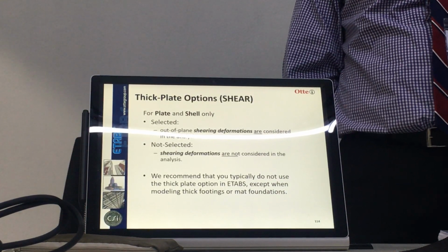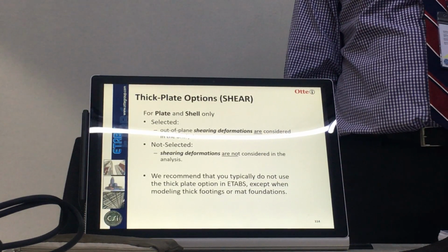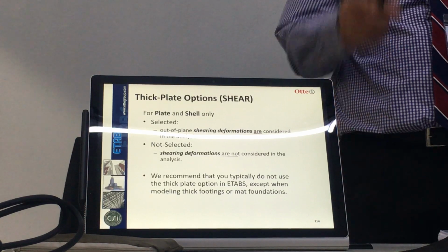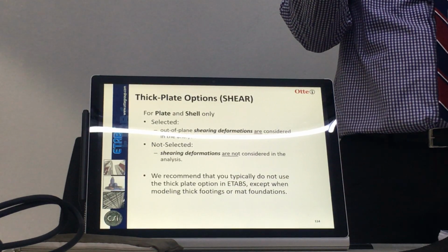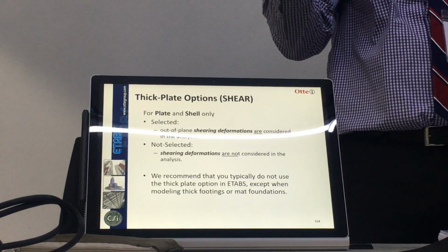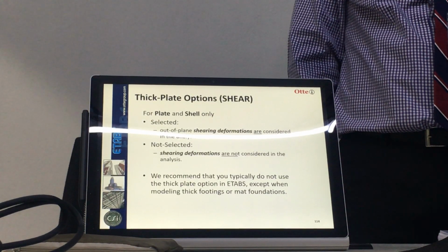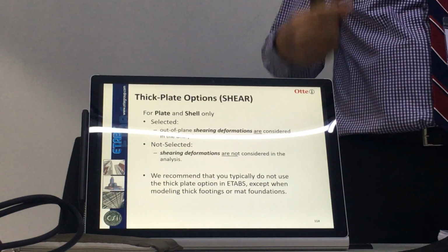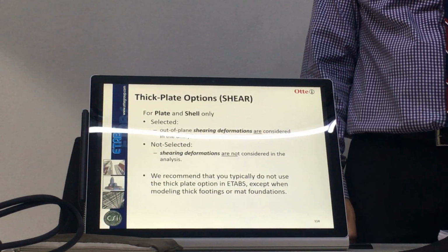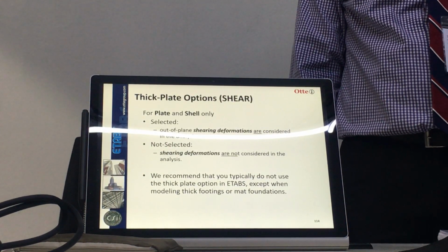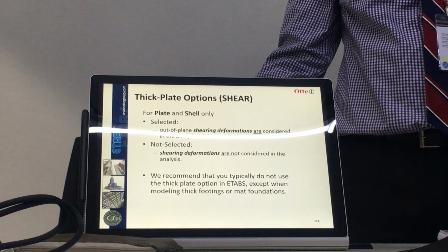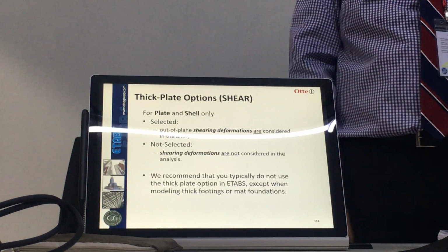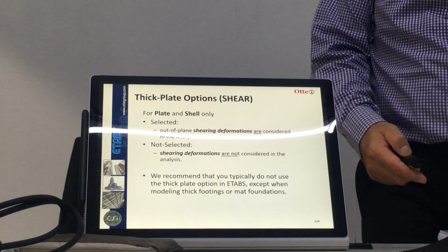But I can tell you this slab here, 200 mm thick, is very thick. Why? Because it spans only 400 mm. The thickness is half the span length. So it's thick, right? That is how we understand it. So when you have an aspect ratio that can result in shear deformation, you use the thick formulation, or when you are subject to high shear, like a rough foundation. Column has high shear, right? So you use the thick formulation.